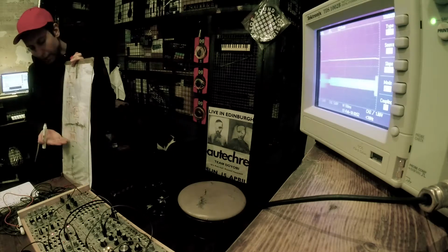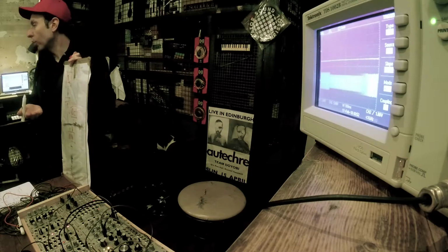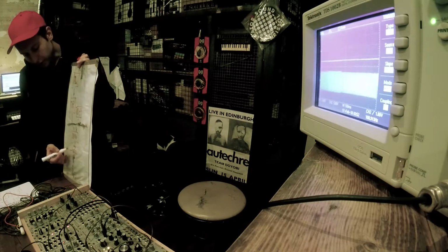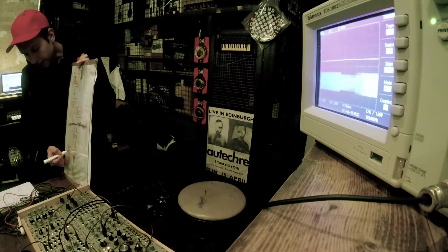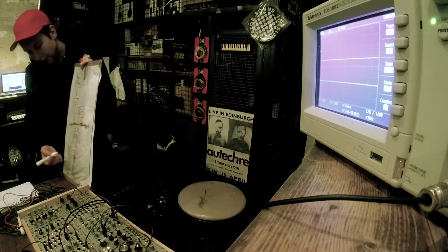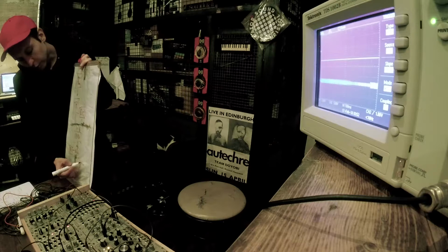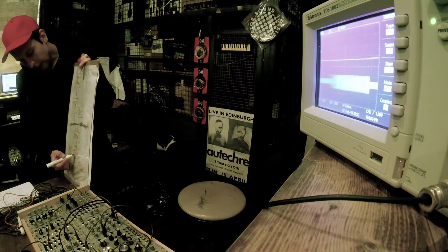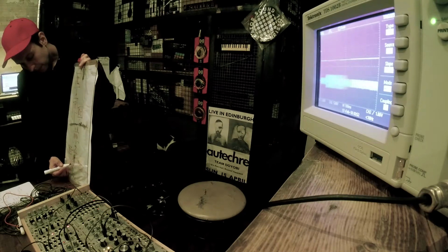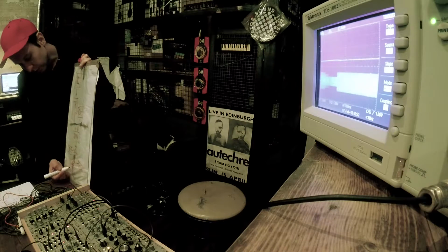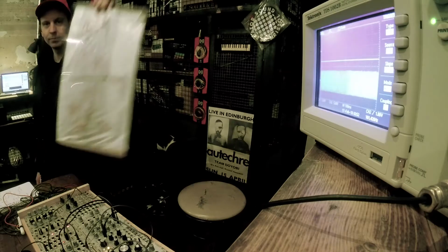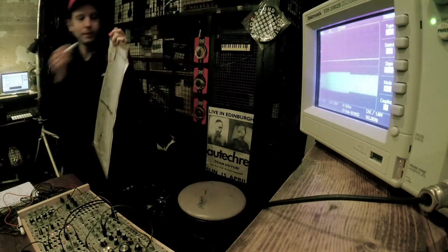So this is my mechanism where I can push up the lower clipping level. Then to this I add another DC voltage, which is negative, to get it back to reach the zero line. Then this signal goes into an oscillator and into a VCA, and that's my output signal. Make sense? Here, for the viewers at home. Okay?